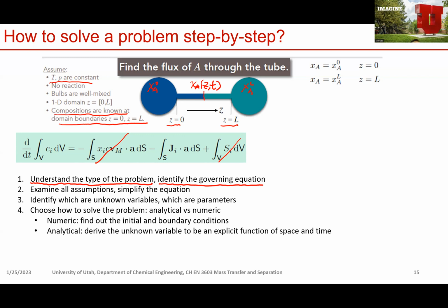This leaves us with a transient problem. We have the dC/dt on the left. If we have that term in our equation, that means C is still dependent on time, which means it's a transient problem. But for simplicity, in today's lecture, we make the pseudo steady state assumption, right? That helps us eliminate this term as well. Pseudo steady state means at some point our system has reached a pseudo steady state, and the concentration does not change with time. That means we can just eliminate this term, right?